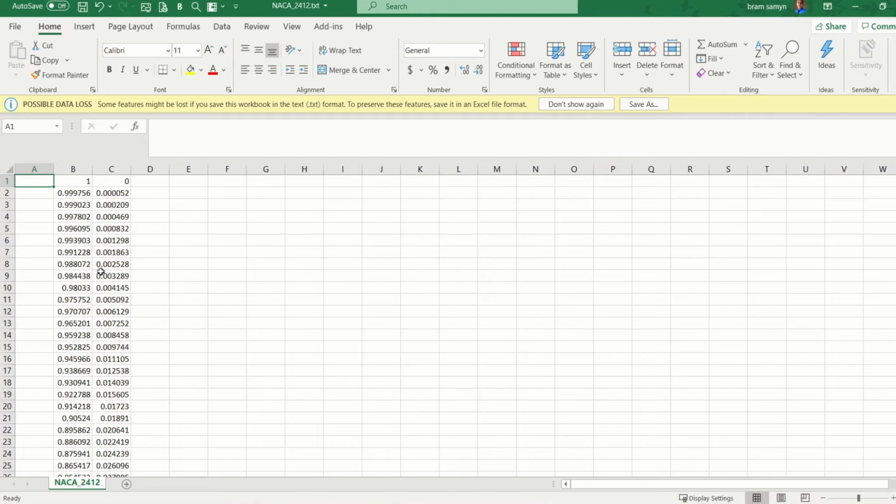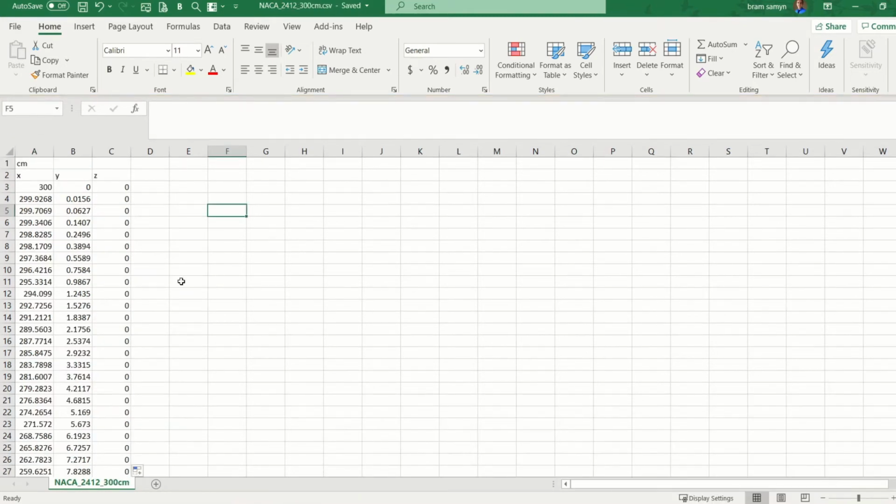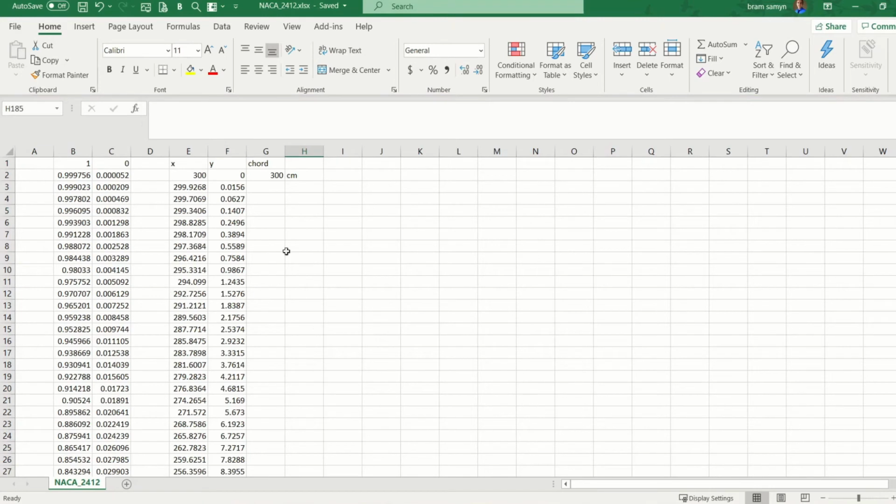So let's go to an example. You will define your chord in centimeters. This is very important because Fusion 360 in its core uses centimeters as its basic measurement unit. In lots of cases you will define everything in millimeters. That's what you did in your settings. Once you start Fusion 360, you will say, I want to use millimeters as my standard unit of measurement. But in the background, Fusion 360 uses centimeters. That is why in some scripts, also the script that we will be using, the unit that will be used is centimeters, and you cannot change that.